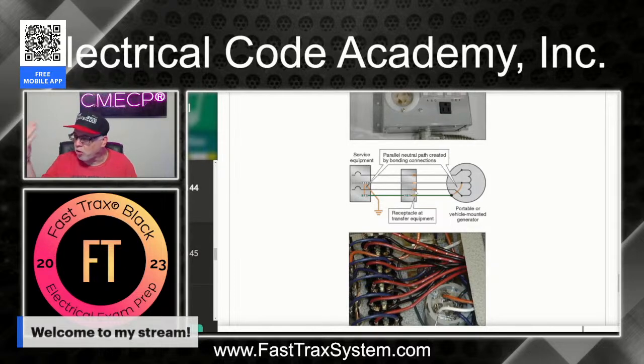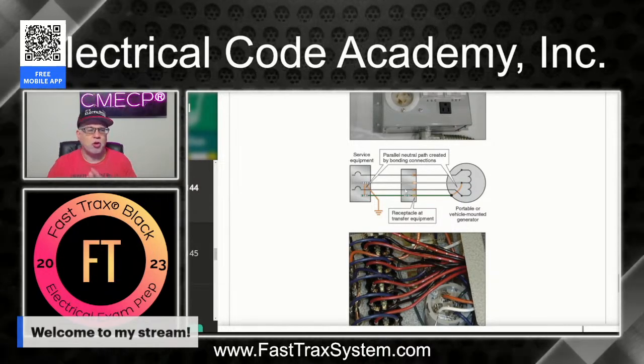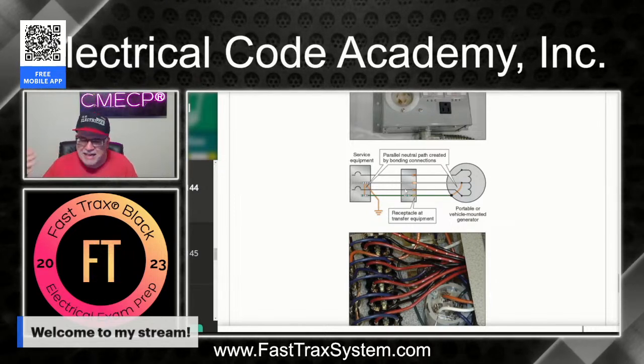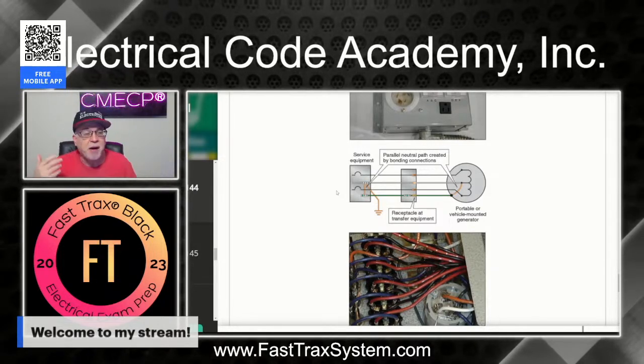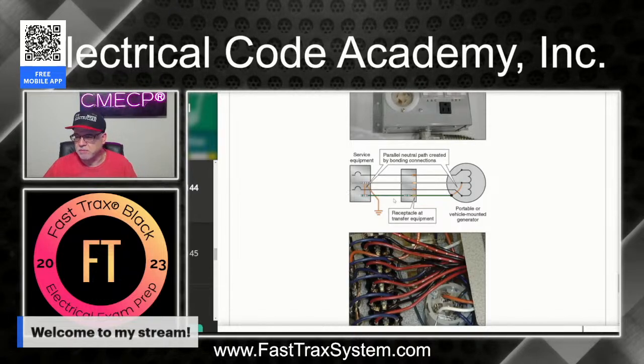And then, of course, all these bonded connections are now going to be energized with neutral current. So it's critical to not just buy components, put them in, buy a generator, and not know what your application is for. So typically, a floating neutral generator would be what you would use on a dwelling, whereas a bonded type generator is what we would want to use as a standalone application, okay?